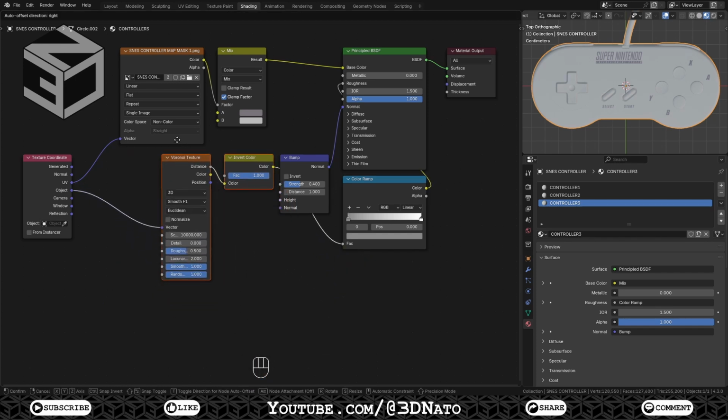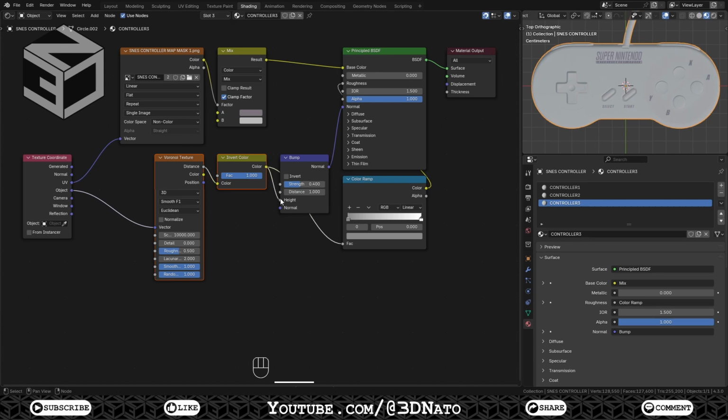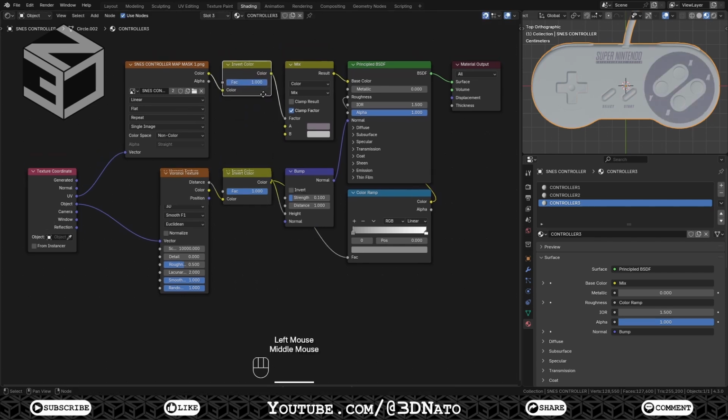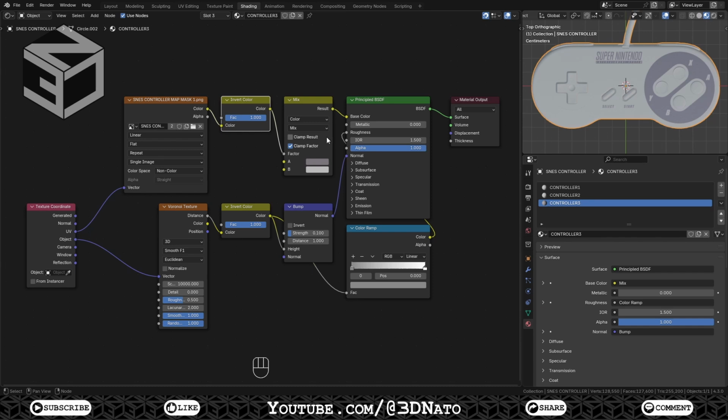Rearrange if you want, connect invert color to bump height, set strength to 0.1, duplicate invert color, and place it between the image texture and the mix color node. Notice that the colors flipped inside that part of the mesh.